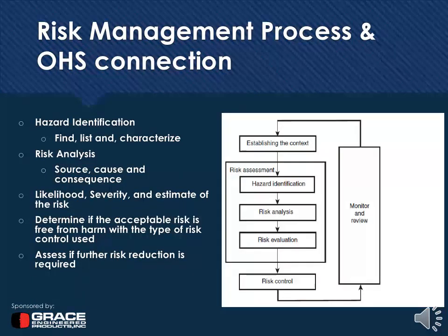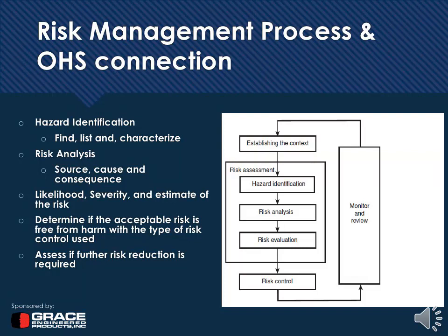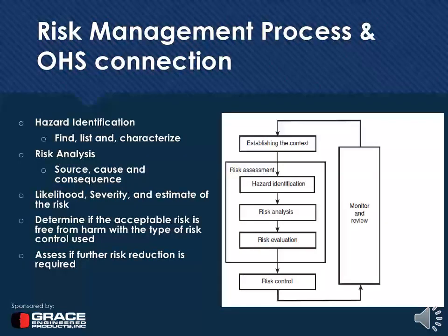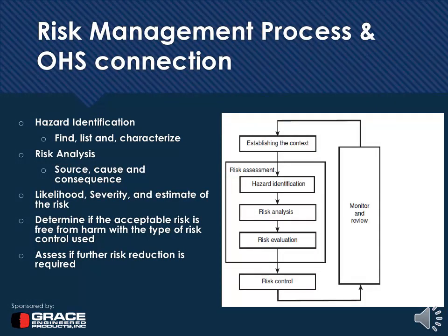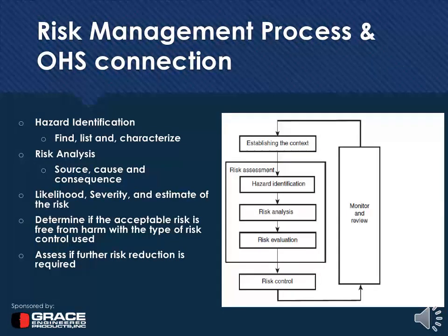This chart shows the risk management process, and it's adapted from the ISO 31000 standards. So this is specifically about the occupational health and safety's objective in risk management. The OHS objective is pretty simple. It's freedom from harm. So how do we avoid injury or damage to health? I would like to bring a quick correlation between NFPA and OSHA. NFPA 70E basically sets the minimum consensus requirements for electrical safety work procedures, and it establishes the minimum standard for care. On the other side, OSHA's electrical safety standards are performance-based. So OSHA validates how this freedom from harm is achieved, and NFPA 70E provides the how-to. So it's more prescription-based, and OSHA is performance-based.